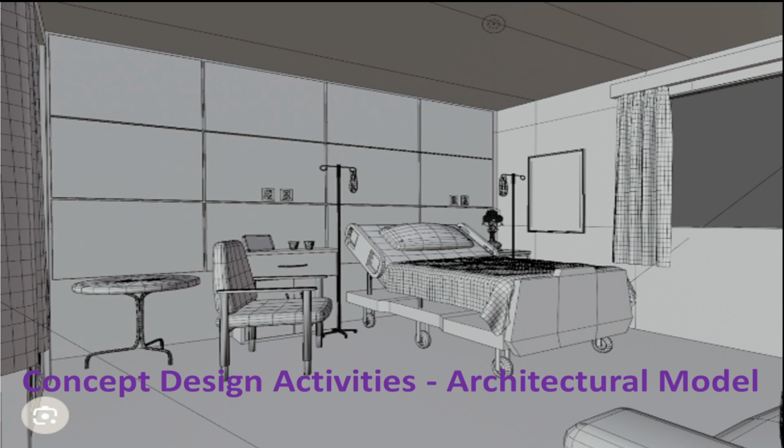Concept design activities: architectural model. Activities that form the framework: schematic representation of existing model as a background starting point; schematic layout of major process architectural elements represented at LOD 100 or 200, like exterior and interior masonry walls, roofs, doors, and so on; approximate layout dimensions, element sizes, and orientations.